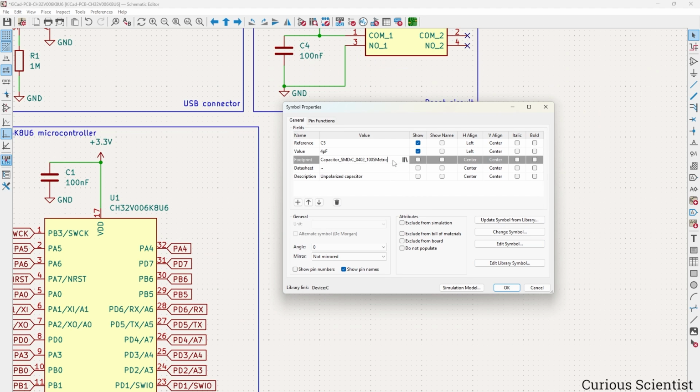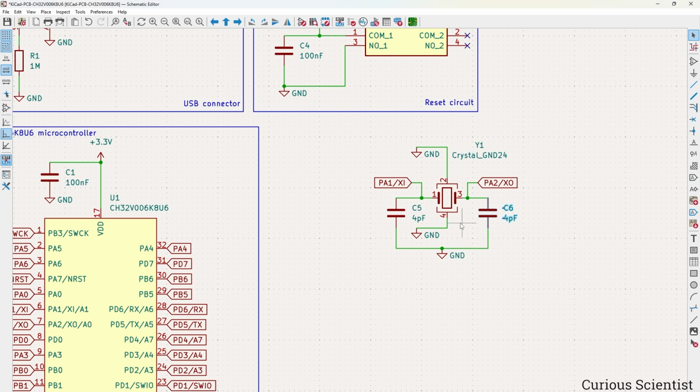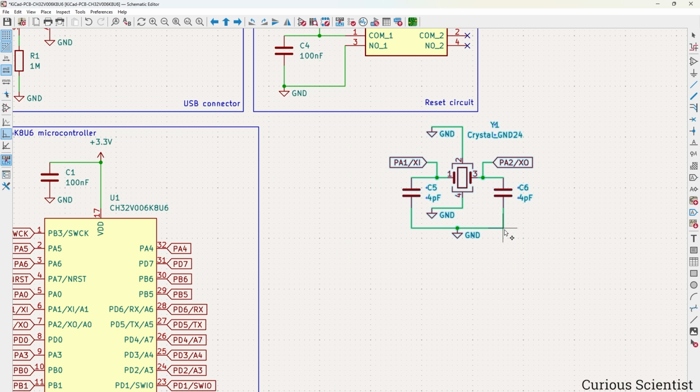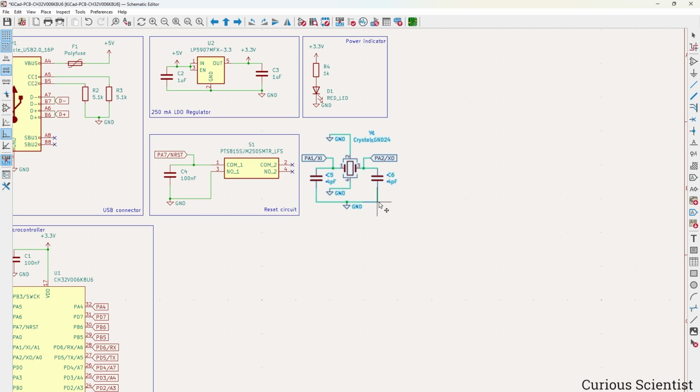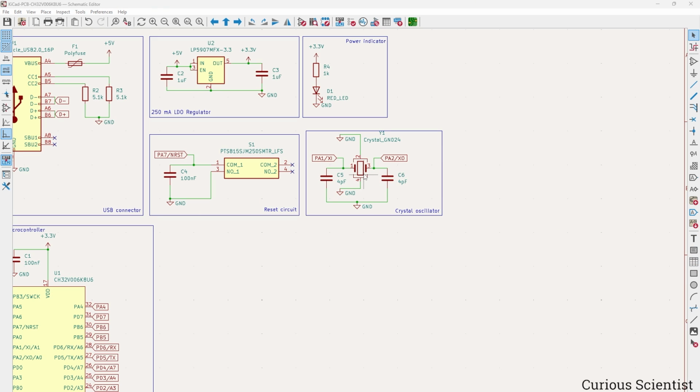And we can do a trick: we can press Control A here, select all, Control C, and then I go to this, and then I just replace it. So I just pasted this text here, press OK. So now both of them have the same footprint. So this is done. Let's put it here and let's frame it. And with this, our oscillator is done.